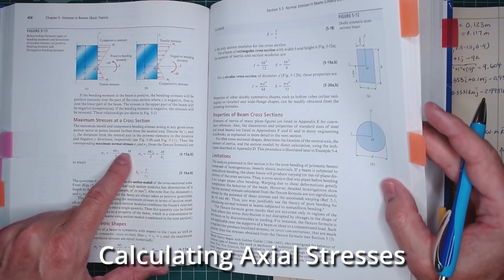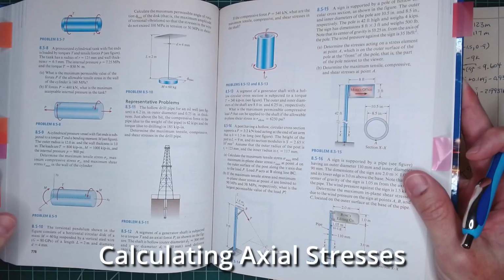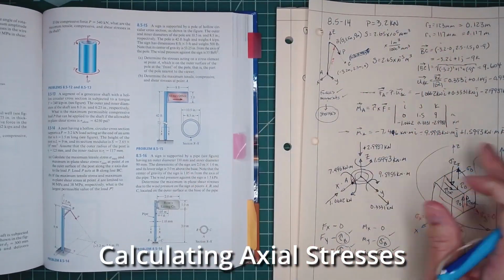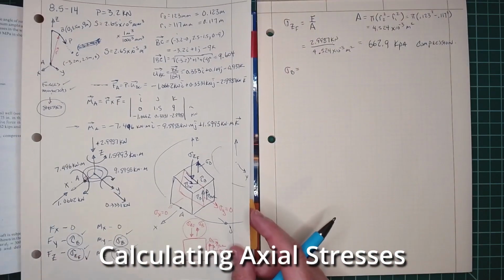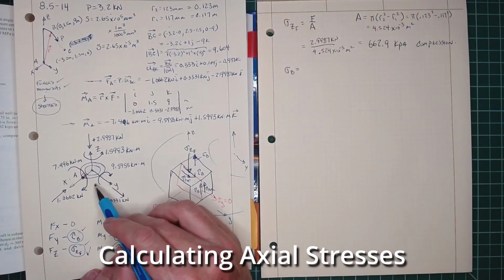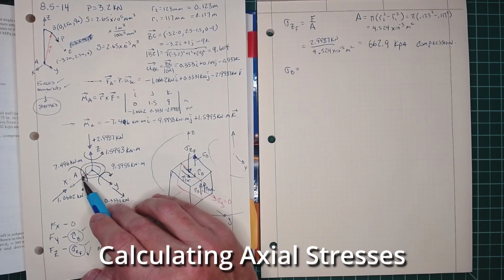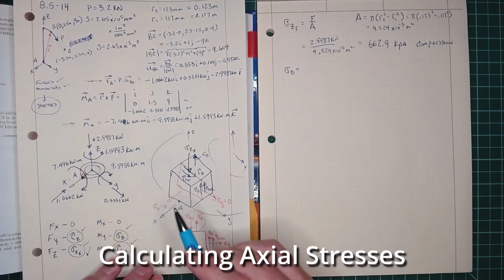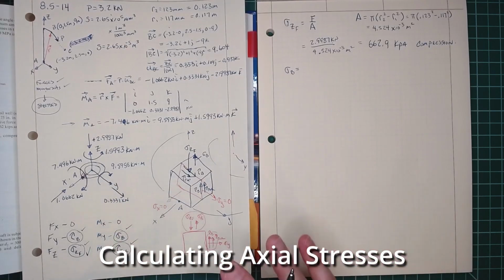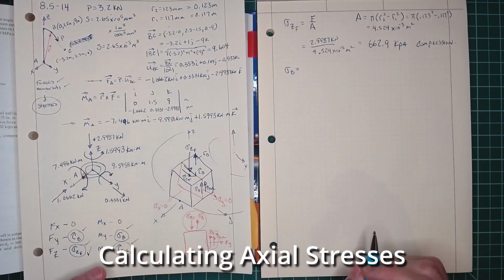Remember, there is a sign associated with this. We kind of did that already a little bit earlier, in that we said the moment is going this way, and it's going to be creating a tensile stress at point A. So we're not going to deal with the plus or minus signs on there. We just know that we're going to calculate this up and come up with a tensile stress.